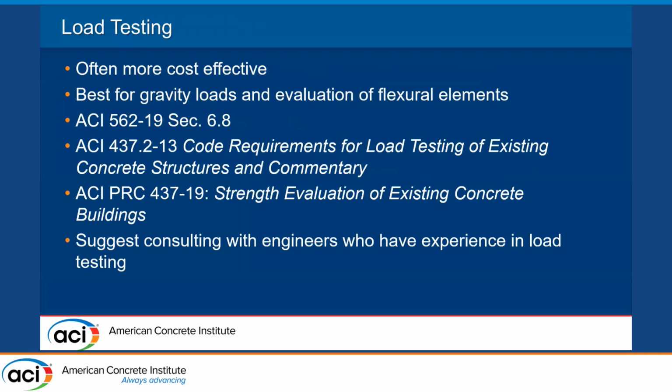Load testing is often more cost effective, best for gravity loads. I think it's best for gravity loads and evaluation of flexural elements. 562 just says, go ahead and use the next one down, 437.2 code requirements for load testing of existing structures. There's a great report by ACI Committee 437, that's evaluation of structures. And again, if you're not familiar with running load tests, please hire an expert who is familiar with running a load test because safety is a major issue in load testing of structures.